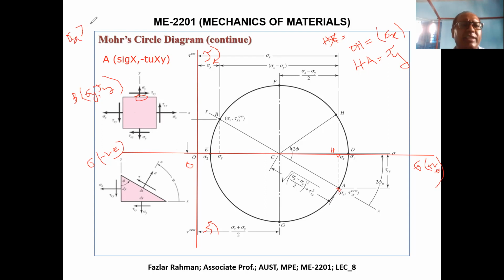So I'm just thinking that the value of sigma x is greater than sigma y. Now I'll put the point B in the graph paper. So if sigma x, sigma y is 30, from the 0 you go 30 units. If it is 10, you go 10 units. If sigma y is negative, you go to the left side. So over here, sigma y is positive. So I can go anywhere, but I just came right over here. This is my sigma y.